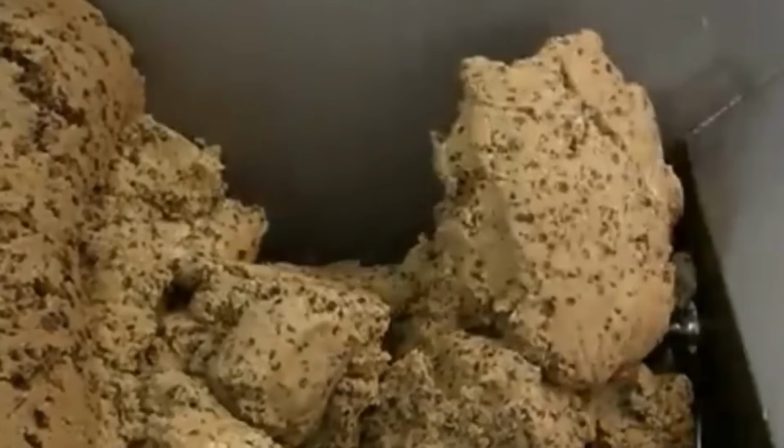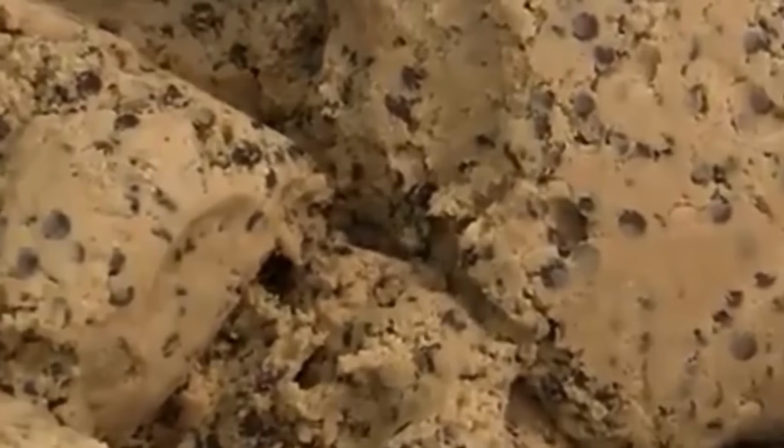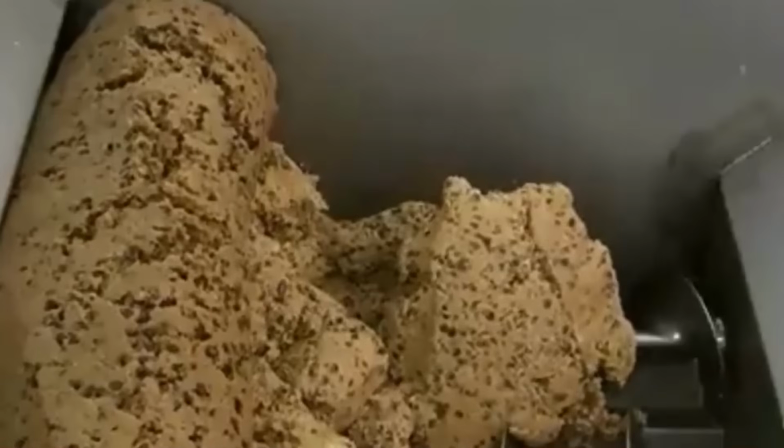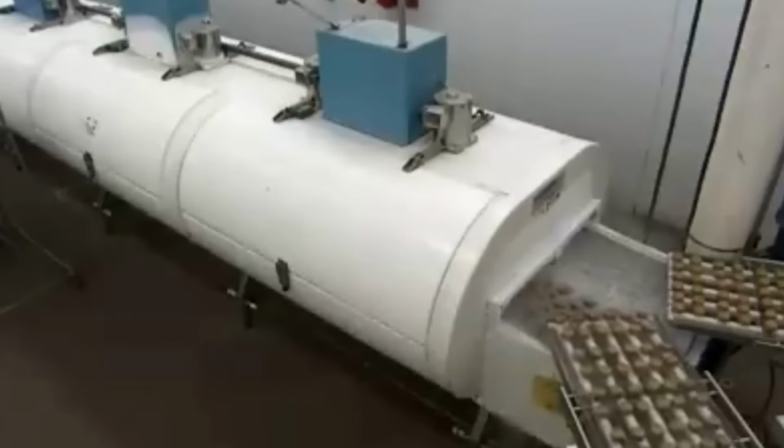All liquid and dry ingredients are tracked using an integrated batching control system that verifies real-time mass flow and batch integrity using load cells and flow meters. Each batch is loaded into a planetary batch mixer with a dual paddle agitator system. Mixing follows a 3-stage time-controlled sequence.